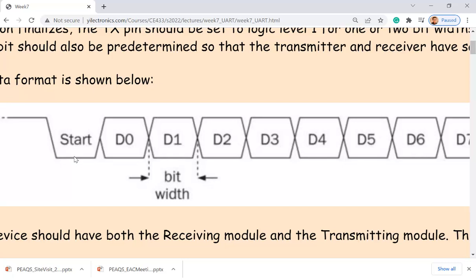Right? You don't want to receive the 0 that started as data. So whenever it hits 50% of the max count, you don't want to do anything. You don't want to save it. It's just a 0 bit from the start bit. It initializes everything and counts for another max to get this one, and then starts counting to max. So eventually you get all the data, not getting this one.